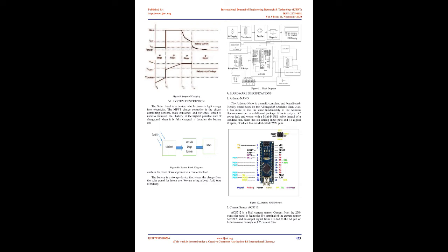Float charging method. Float charging is the most commonly used method for backup and emergency power applications, where the battery's discharge is not frequent. During the process of float charging, the charger, battery, and load have to be connected in parallel. The charger operates off the standard power supply, which provides current to the load during operation. In the event of a power supply failure, the battery provides backup power until the regular power supply is back. Since most equipment requires alternating current, a rectifier circuit is usually added between the battery and the load.